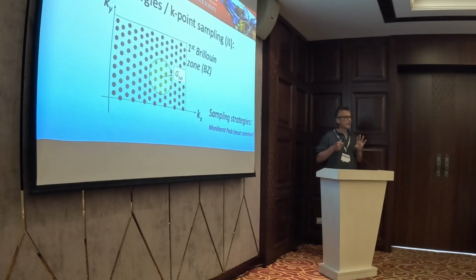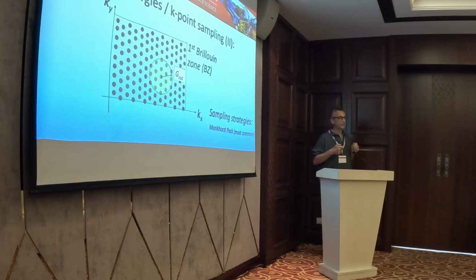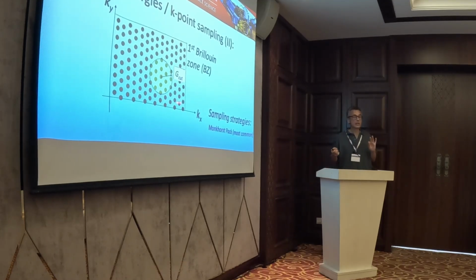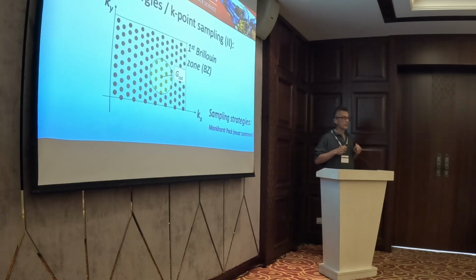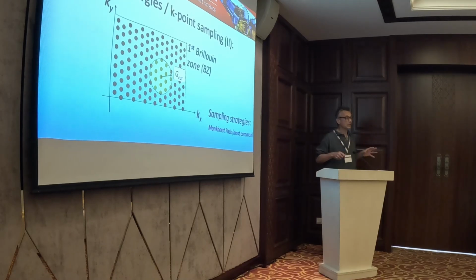Now there's a lot of theory going in there. And what I want to do is give you this concept because, again, when you look at a DFT package, you'll see a lot of parameters. And you'll be thinking to yourself, where did these parameters come from? These are a couple of them, and some of the most important ones that you'll find when you actually do a calculation. Because if you don't use enough K points, you won't get a very accurate calculation. If you don't use enough terms at each K point, again, you won't get a very accurate calculation.